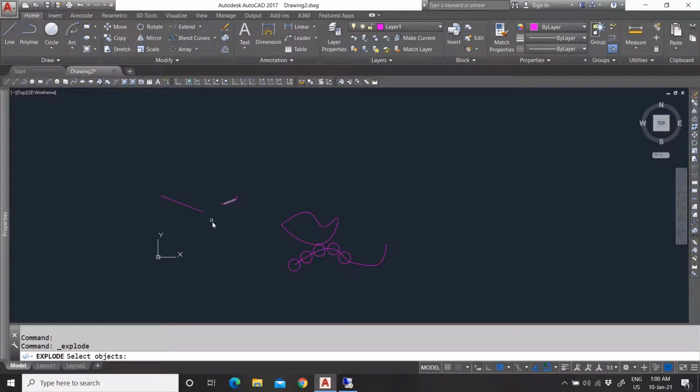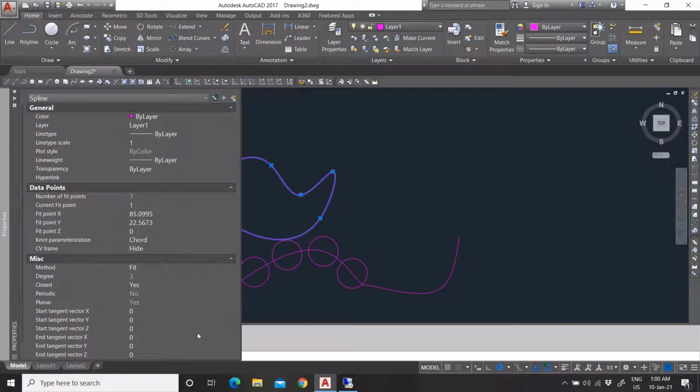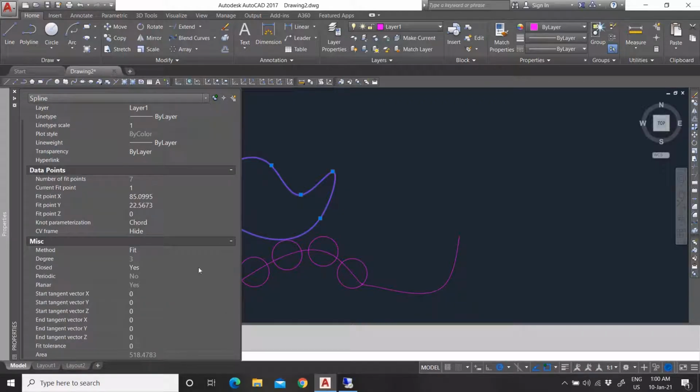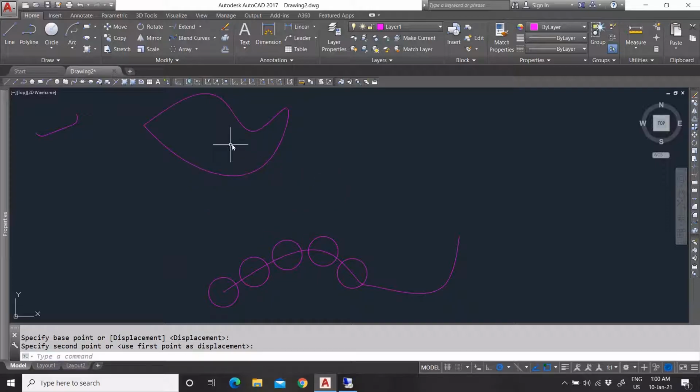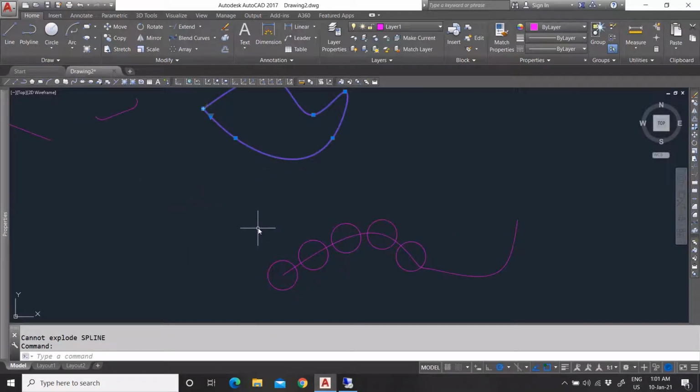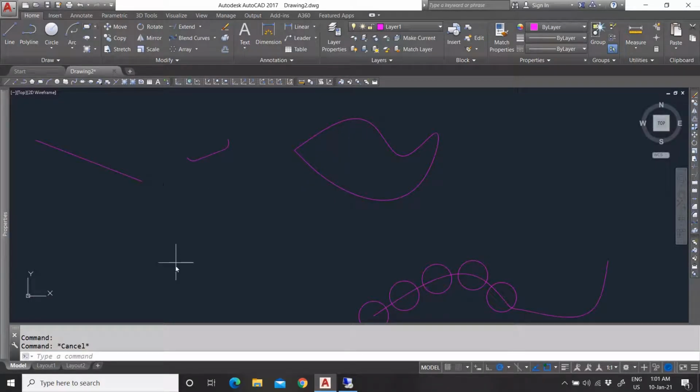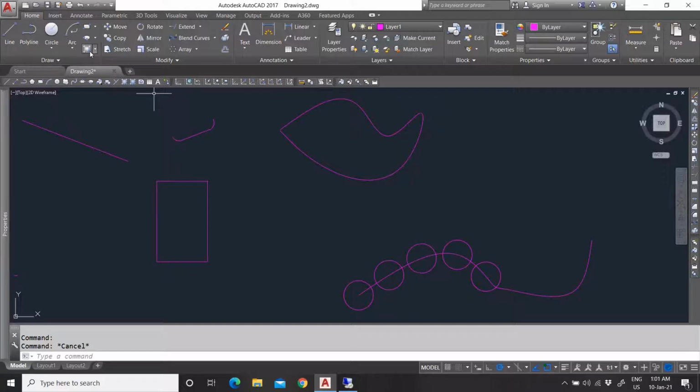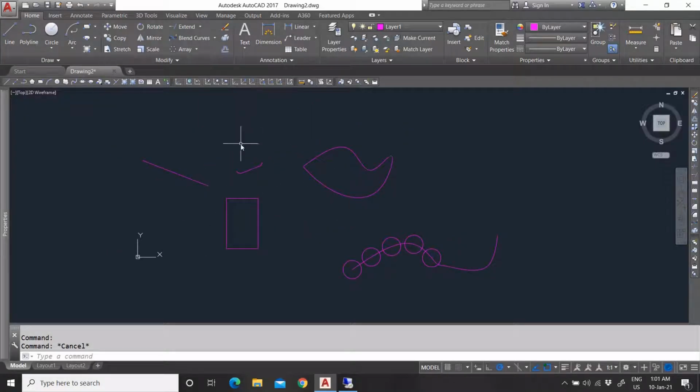Explode: let's say you have this spline right here and this spline is closed. So this is a closed object. Now, if I select explode, select that object, click next, and then it will explode it. Oh, it did not explode this one. Let us just draw a box then. Explode, press enter, and it will explode my whole polyline into separate lines. That is the opposite of what my boundary did. Now it exploded my objects into all separate loose objects.